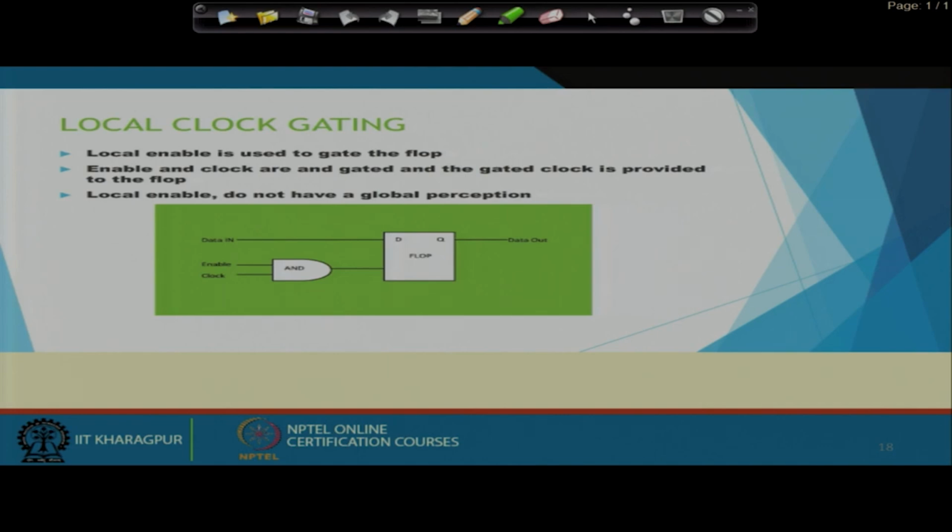So, at that time, inside the chip, as the power supply and the clock are already there, the audio processing block will also be active and contribute to the overall dynamic power consumption. So, for this particular condition, whenever I use the video processor, you shut down the total audio processor block, so that the power consumption becomes very minimal at that time.